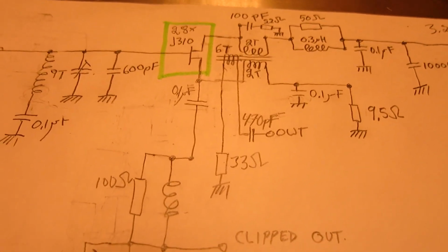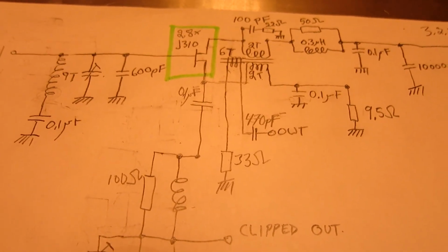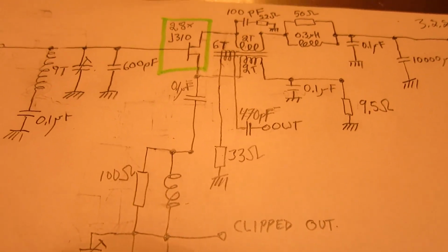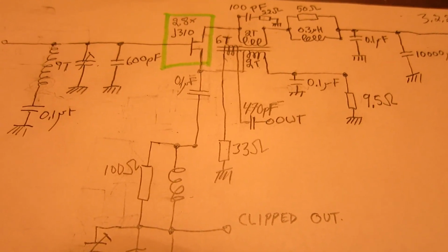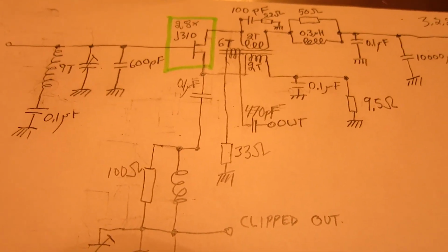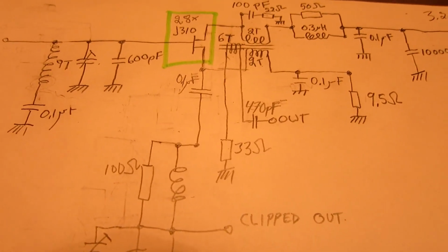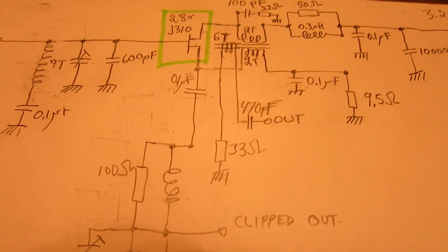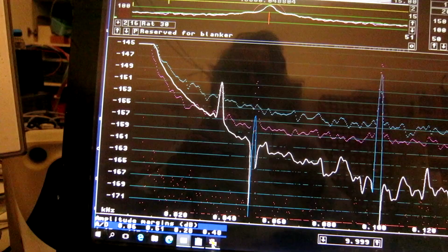So now I will study a little bit more carefully how sideband noise is related to the current through the transistors and possibly also the voltage. And it's the power amplifier I am looking at, because the phase noise is okay, and what I'm adding in the power amp is just amplitude noise, and I want to make that a small addition.